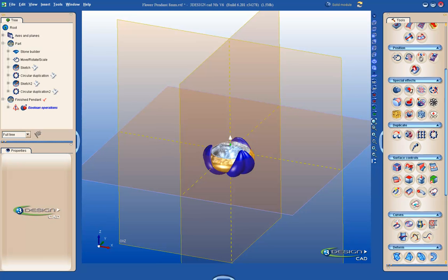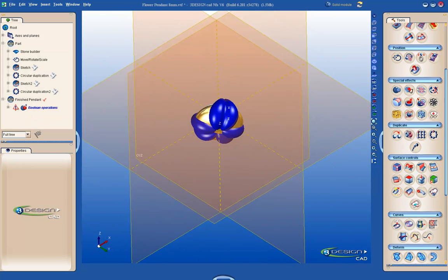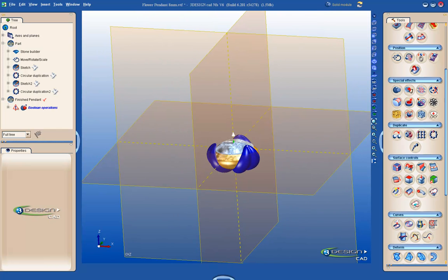If you'll notice, off to the side I have an exclamation point. If we hold our mouse above that, it says, warning, geometries have been slightly moved to avoid failure of this Boolean operation. This is one of the few warnings we can get in the tree that is okay. Our object is still solid, it's valid, it's just when the Boolean was being performed, the computer had to change some of the geometries ever so slightly to keep there from ripping it open or not being a solid object. It is absolutely fine in this case.